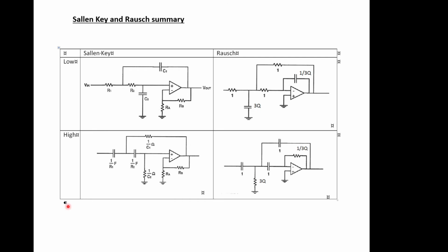But once you've done it a couple of times, it does become very easy. So what I would say is just try and design some arbitrary filters. Say you want to pick one that has a cutoff frequency of, say, 3 kilohertz or something. Try and design one that does that, put it in the simulator and just check it all works properly, and then design a high pass filter, put it in the simulator and check it all through.